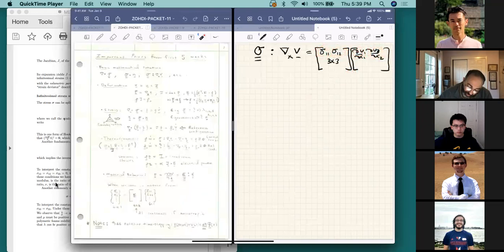And it, of course, appears in a very important equation to us, the first law of thermodynamics, which states that the density multiplied times the stored energy per unit mass is equal to the stress power, this guy right here, times the gradient of V minus the divergence of Q plus the mass density multiplied times the number of sources, or the sources of the material that are being added to the material. And of course, this could be lasers and other stuff, and it will be when we start to get to that.